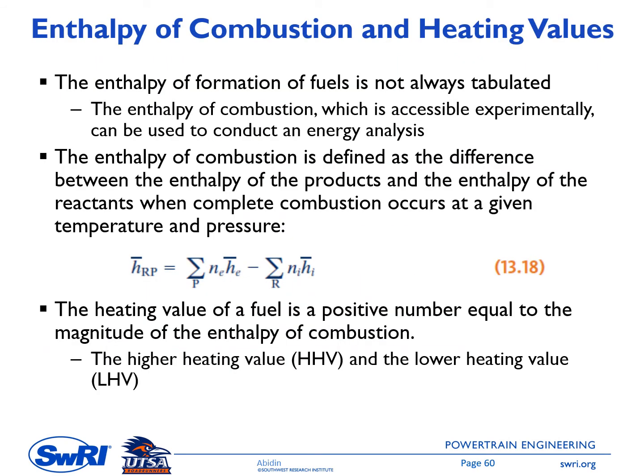Next topic is enthalpy of combustion and heating values. The enthalpy of formation of fuels is not always tabulated. When that happens, we can use the enthalpy of combustion to conduct an energy analysis. And this enthalpy of combustion is accessible experimentally. The enthalpy of combustion is defined as the difference between the enthalpy of the products and the enthalpy of the reactants when complete or stoichiometric combustion occurs at a given temperature and pressure. And the enthalpy of combustion is formulated with this equation 13.8.